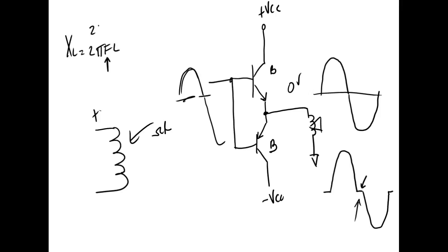Because when you measure those, an 8 ohm speaker is going to measure less than 8 ohms. Why is an 8 ohm speaker going to measure less than 8 ohms? Because it's X of L. It's impedance. It's not a resistance, it's impedance. Car speakers are set at 1,000 hertz. So the impedance of a car speaker is what you get at 1,000 hertz. So you'll measure less than that, probably around 5 ohms. Look, an 8 ohm speaker will probably measure around 5 ohms DC.